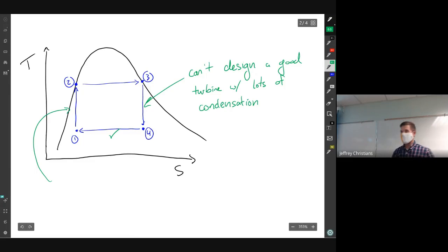So here we have a pump. What we have coming in is a vapor liquid mixture. So it has vapor in it and it has liquid in it. We have a mixture of a gas and a liquid, and it's just functionally hard to design a compression system that works with that. Because gases, you can design something that works just with gases. You can design something that works just with liquids, but when they're mixed, because their properties are different, you just can't do it.